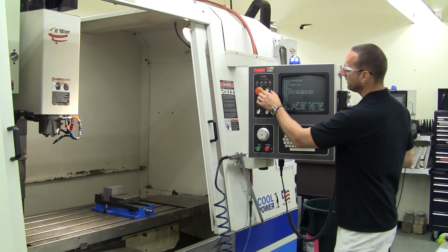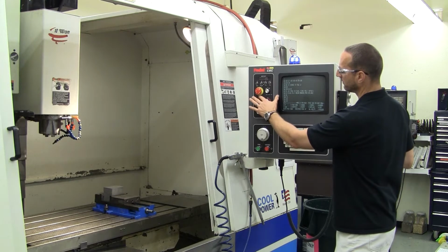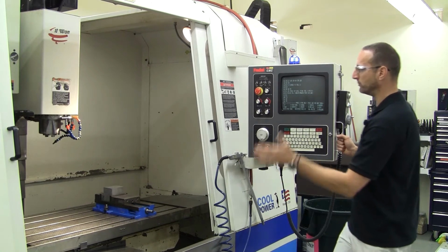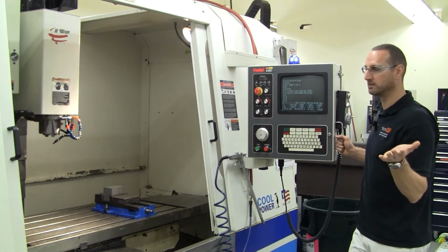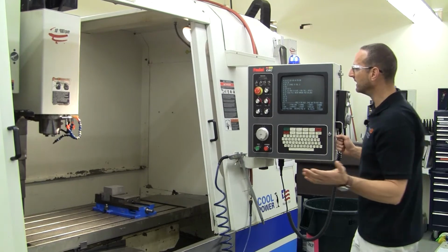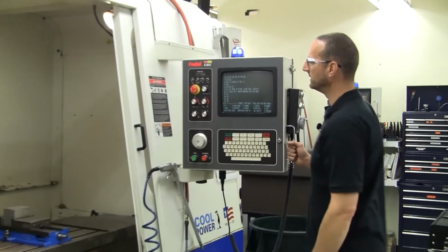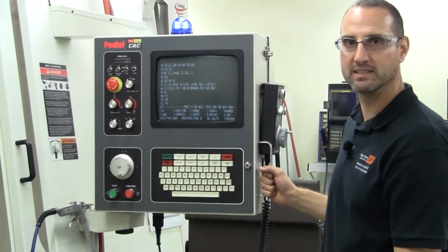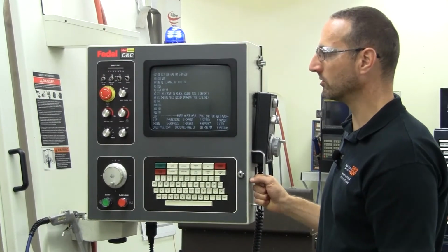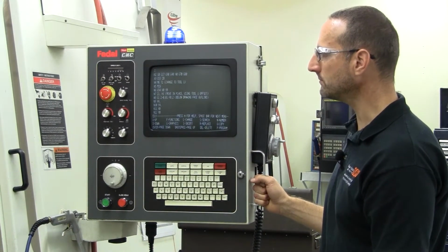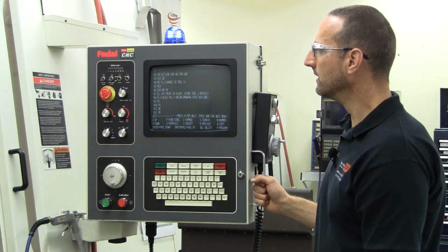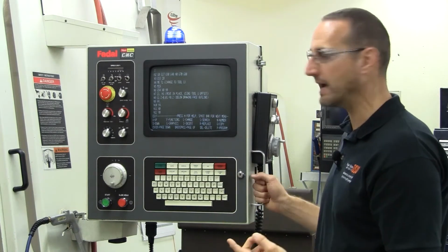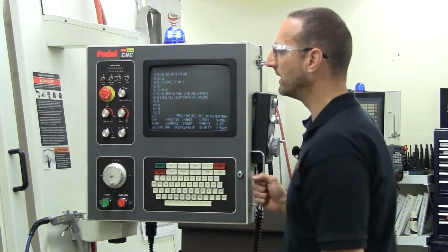Okay, we have a couple other things to go over remaining on the controller. Of course, the emergency stop. Anytime that you need to stop the machine because something unplanned is happening, you can hit this E-stop button, and you will not damage the machine by doing it. Now, this is not the preferred method for pausing a program or stopping a setup routine, but if a situation arises where you need to stop both the spindle and axis motion, you can push this button and you won't damage the machine.